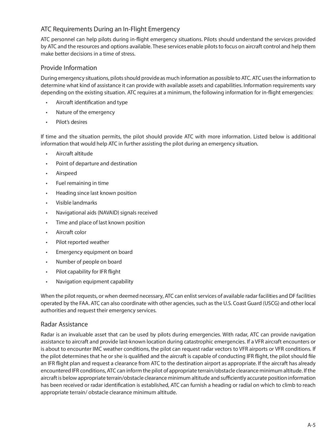Provide information during emergency situations. Pilots should provide as much information as possible to ATC. ATC uses the information to determine what kind of assistance it can provide with available assets and capabilities. Information requirements vary depending on the existing situation. ATC requires at a minimum the following information for in-flight emergencies: aircraft identification and type, nature of the emergency, pilot's desires if time and the situation permits.